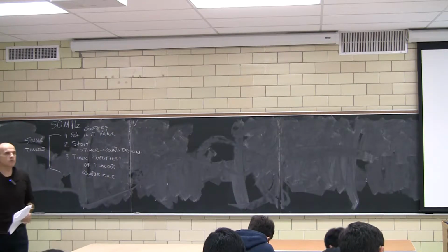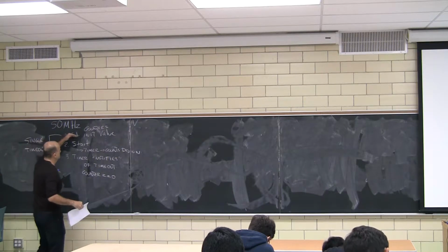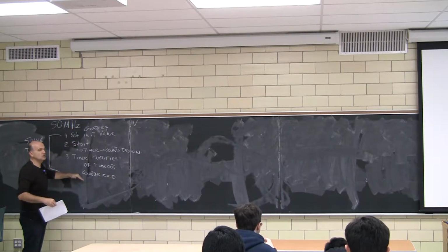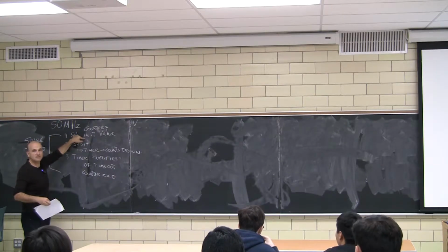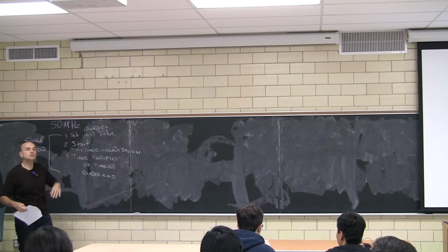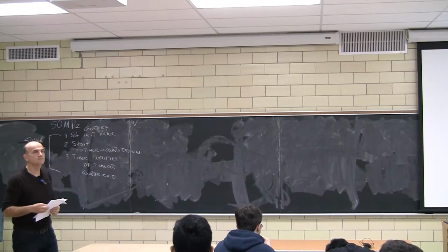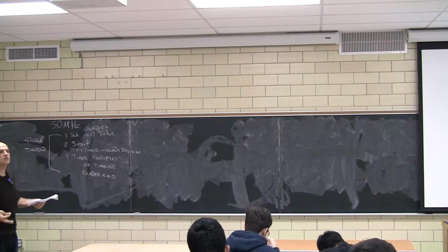There is an alternate mode where it's continuous. That is, you set an initial value. The counter starts, once you tell it, counts down to 0, raises its hand, then automatically resets the value to this and starts counting again. It's up to you to go and look that it has timed out. So far, so good? Any questions about this stuff? We're going to do an example to see how it works.